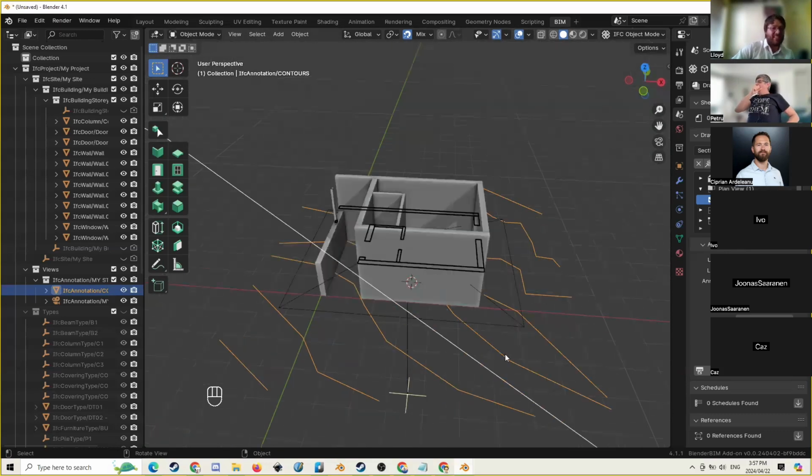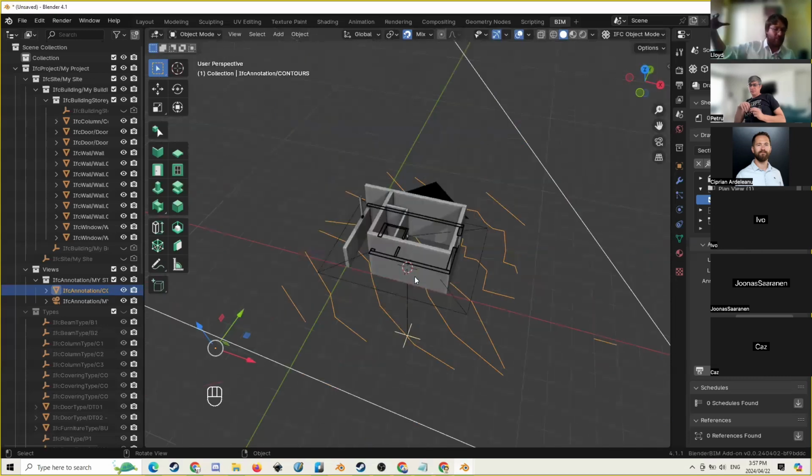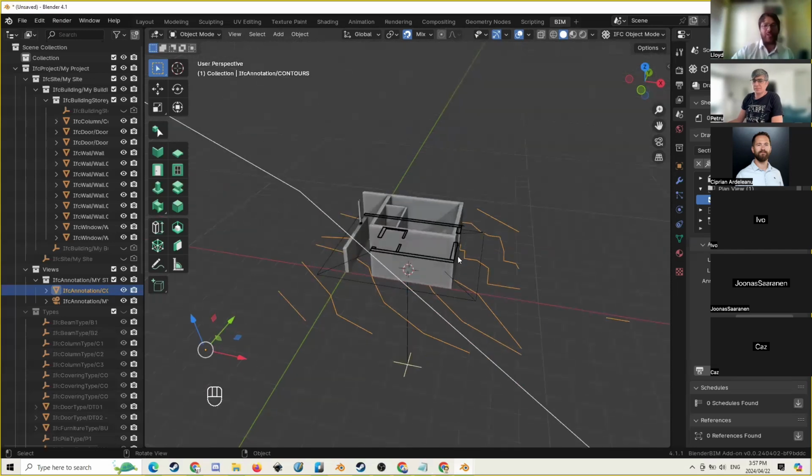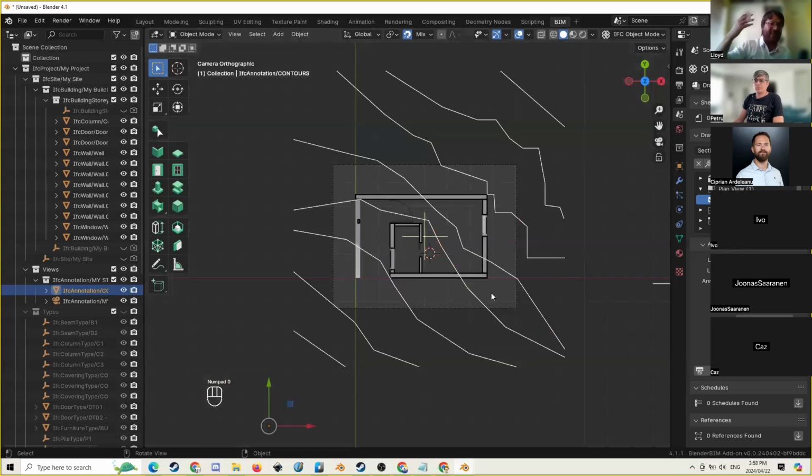So this is just to store the correct reference information, because this contour being at that point, at that corner, is probably not going to be the case once I make the 3D terrain and then loft the shape, essentially, unless it's manually modeled, which is not necessarily how you want to do it. But yes, Petru, I would store an actual model of a 3D space with the actual heights in addition to the 2D information, but use the 2D information as a reference so that I don't have to keep loading it in, and so that it represents itself properly in the 2D space.